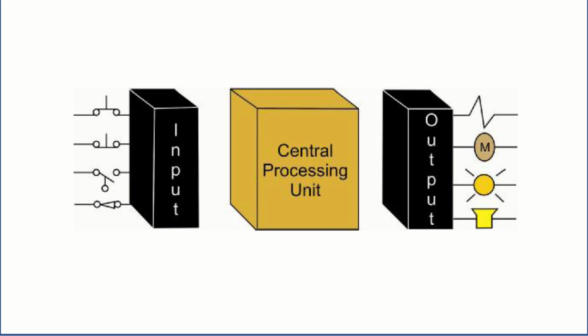That means that unless there is a change of 5 volt at the input side, the PLC will not be able to detect the quantization. So this is the important thing, that now you are able to understand that if we want to read signal from that particular transducer, then this PLC is not going to suit the purpose.